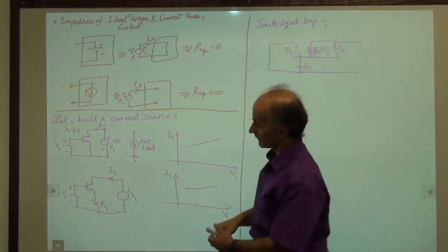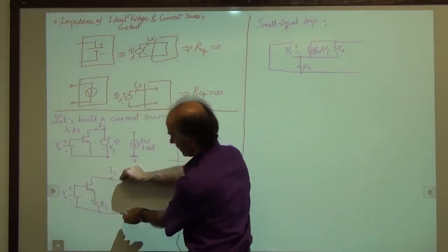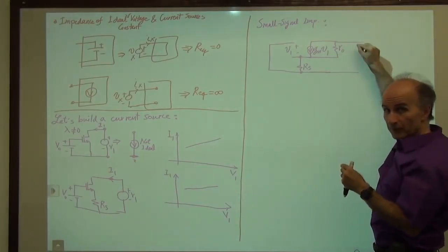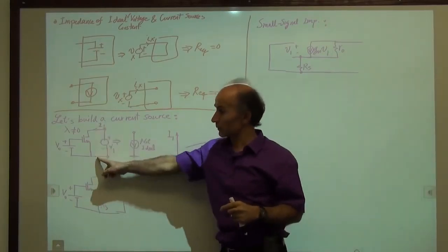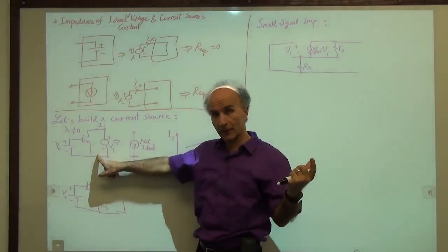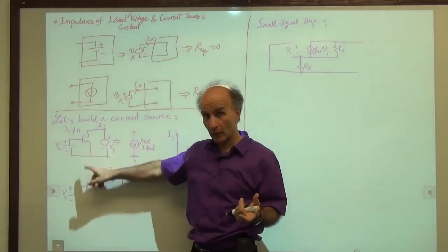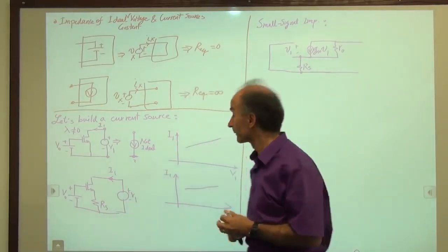So as far as the circuit over here is concerned, these two wires will be these two wires, and we would like to find the impedance between these two. We already found the impedance between these two. We know from our previous calculations last time that that is just equal to RO. Now we're hoping that this will be greater than RO of the transistor.